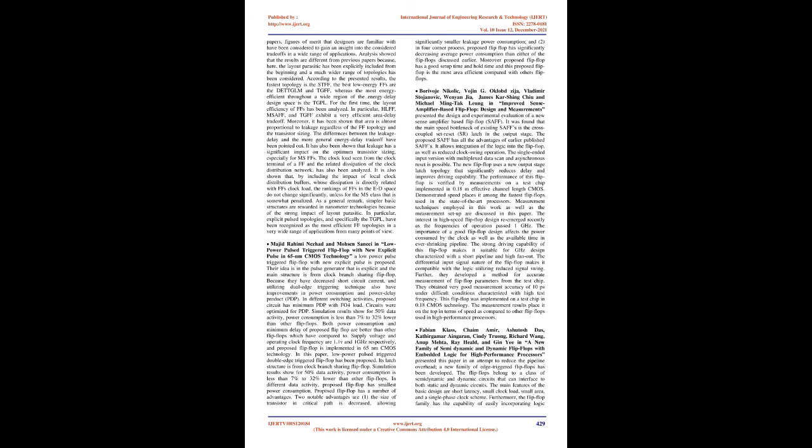The proposed flip-flop has a number of advantages. Two notable advantages are, 1. The size of transistors in the critical path is decreased, allowing significantly smaller leakage power consumption, and 2. In four-corner process, the proposed flip-flop has significantly lower average power consumption than either of the flip-flops discussed earlier. Moreover, the proposed flip-flop has a good setup time and hold time, and it is the most area efficient compared with other flip-flops.